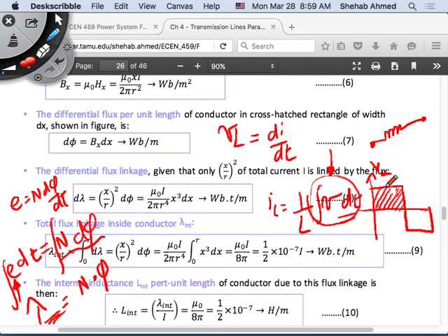Because if you keep charging a capacitor, the voltage keeps rising, and you cannot keep the voltage rising because the dielectric will have a breakdown strength. So what you do with capacitors is you charge them and discharge them if you would like to maintain a certain voltage. Same thing with inductors. Inductors help you maintain a certain current. You place voltage across the inductors, and flux will build up around the inductor, in this cycle.